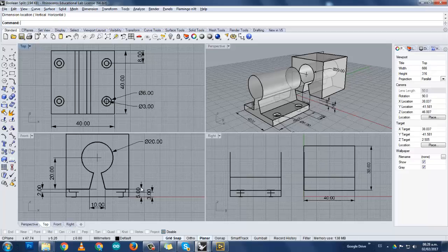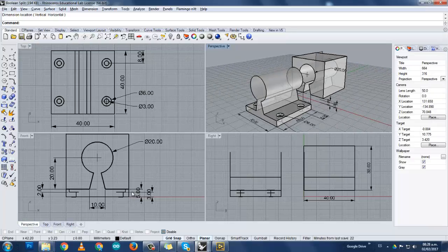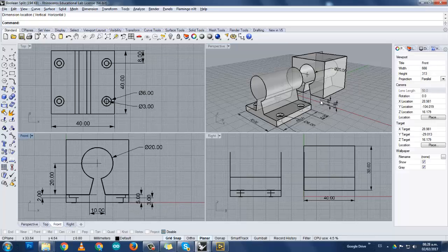You're going to draw this line and then create the surface. After you create the surface, split the two objects, and after you split the two objects you make these 4 holes. Now you have the depth of each hole, and you have the diameter of the hole and the distance from the center. Okay, so that is what you need to do.